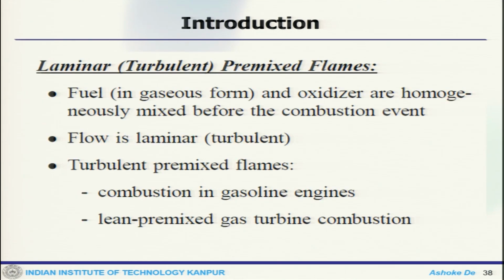Now, if we get to the details of this laminar or turbulent premixed flame, what exactly it is. As the name suggests, premixed means your reactants are of two types: the fuel and the oxidizer. They are premixed before they are injected into the combustion chamber. That is why the premix comes into the picture, where things are mixed before injection.